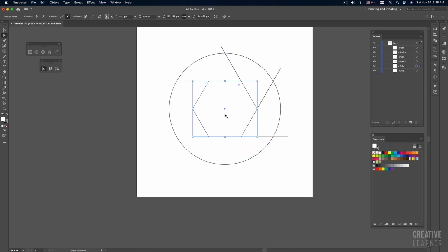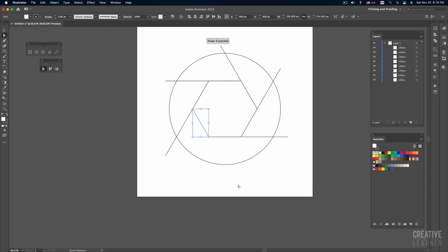Same thing here, Command C, Command F. That is copying one side of the hexagon, and then selecting one point. I will continue, and running around doesn't matter. Slowly come back, and then boom, when you snap it, bang. You have the pink line, saying that you are in a straight line extension. I will let go of my mouse. After that, I will continue here. Same thing, Command C, Command F. I have this point, and then I will extrude it like that. When I exceed the circle, outside of the circle, I will let go of my mouse.